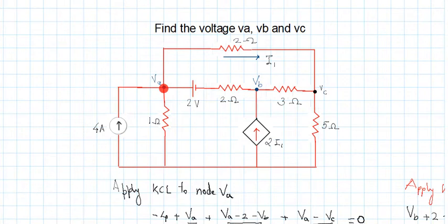Right. So we have assumed what? That all the currents are outgoing currents. So look at the first one now. What is it? It's a current source, right? And the current is an inward current. What we have assumed at this particular node is that all the currents are outgoing currents, whereas this current is an incoming current. It means that it is in a direction opposite to our assumption, and hence when we consider this 4 amperes, we should give it a minus sign, right?